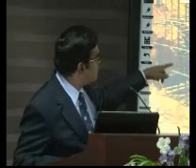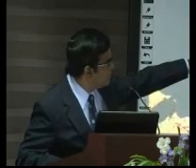These are the two columns at that particular location under construction. This is the complete structure. Then after launching the beams, you can clearly see there that the material is not supported. It is coming through that. That is why it's called a spill-through abutment. Then, after the filling, you can see a natural slope is maintained.